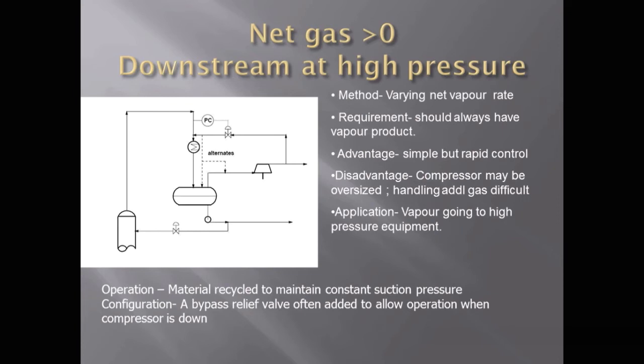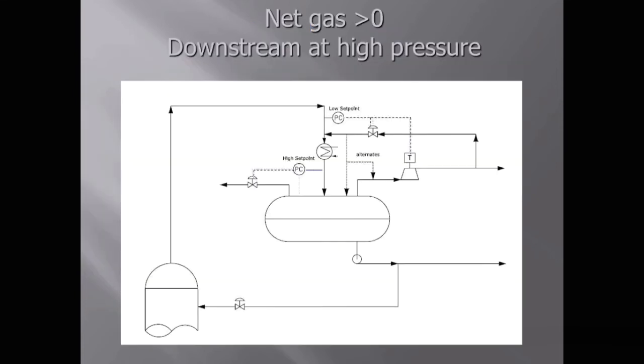So we have a turbine driven compressor which pushes out the gas from the overhead receiver, and the speed of the compressor is governed by the pressure in the overhead line. So as the pressure increases, the speed of the compressor goes up, compressing more gas and pushing it down. And when the pressure is low, from the discharge of the compressor, a recycle line spill back joins at the column top, and this will maintain the pressure. This is a small variant of the earlier model.